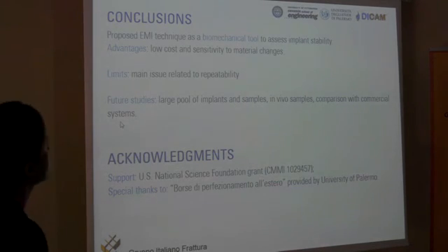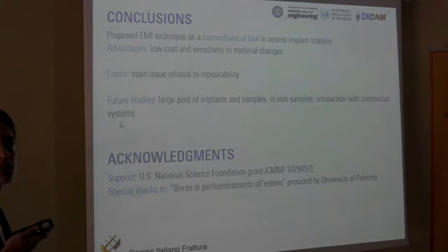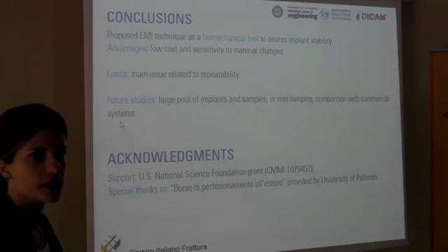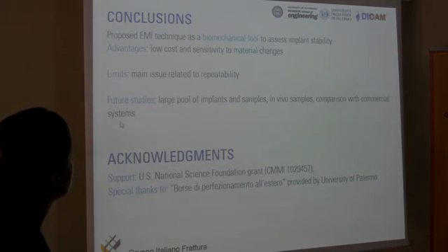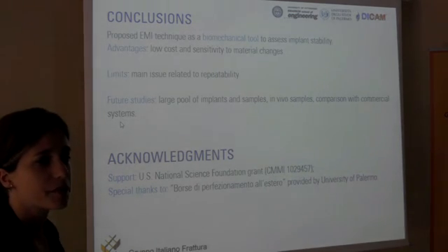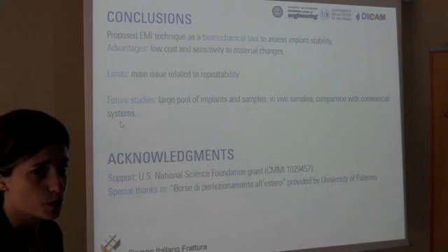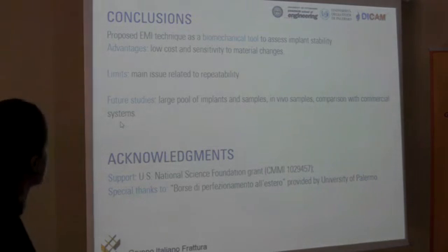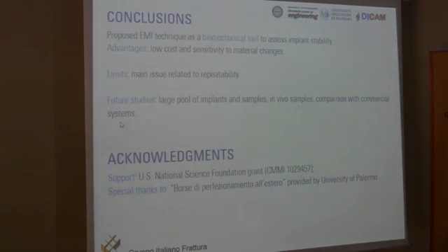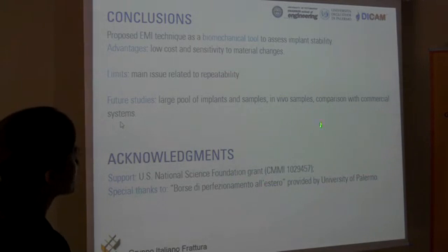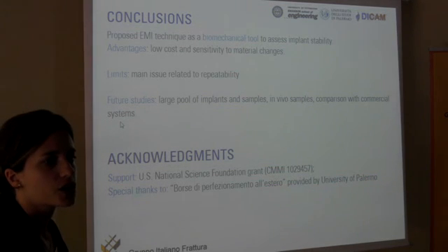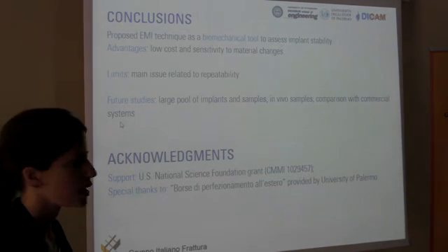To conclude, we used this technique, and it turns out that it was sensitive to the change of the properties of the interfacial tissue between the implant and the bone. There are some advantages of low cost and sensitivity. Maybe the limits are the repeatability, and also the fact that we have to bond the piezoelectric to the structure. Future studies have to be done using a large pool of implants, and also using in vivo samples, and a direct comparison with commercially available systems would be very important.